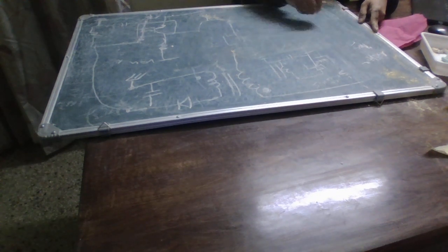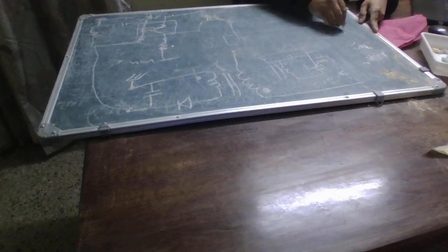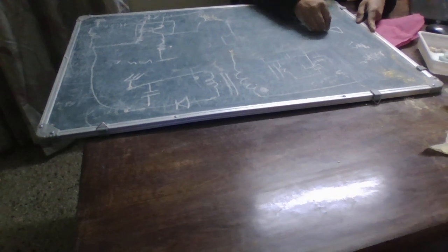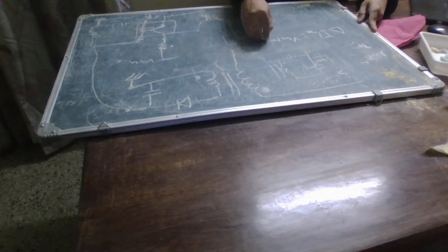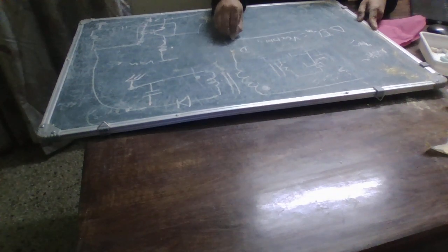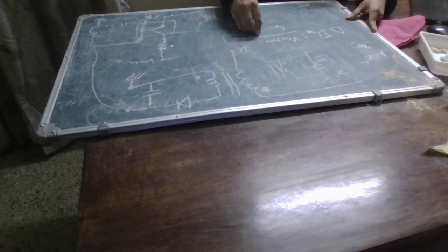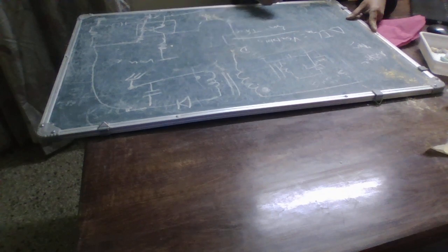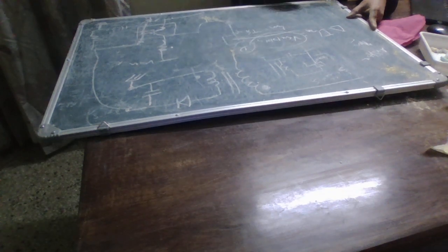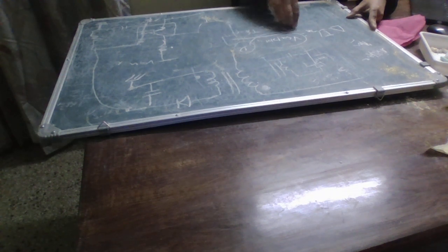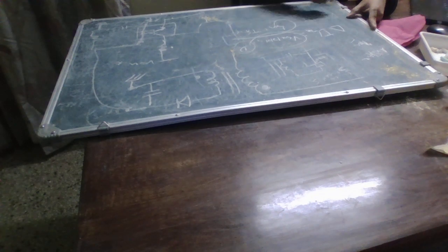To calculate the ripple current, delta IL M is equal to V supply times D by LM times switching frequency. We know the supply is 18 volts. The D we have calculated in the previous part. We have just calculated the LM. Switching frequency we already know.